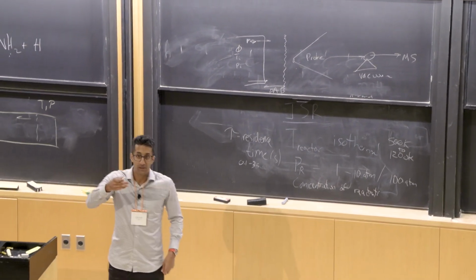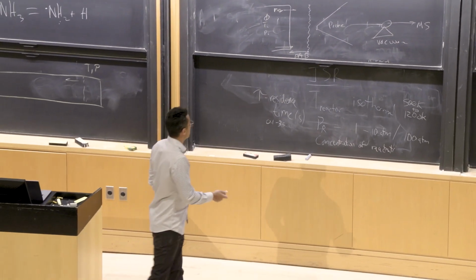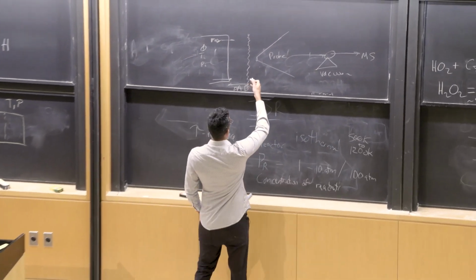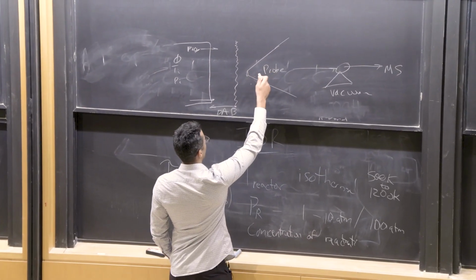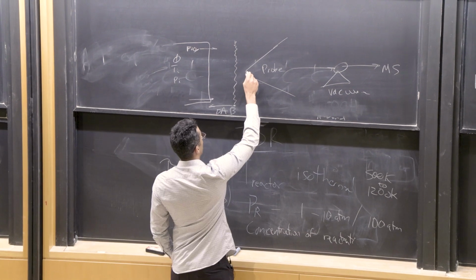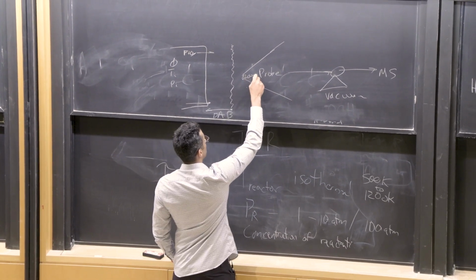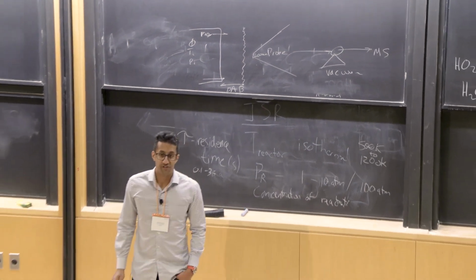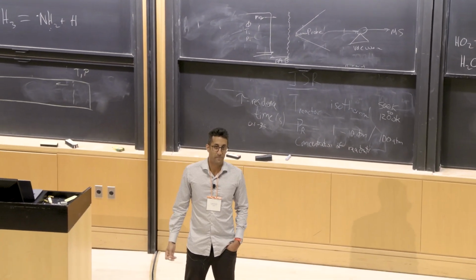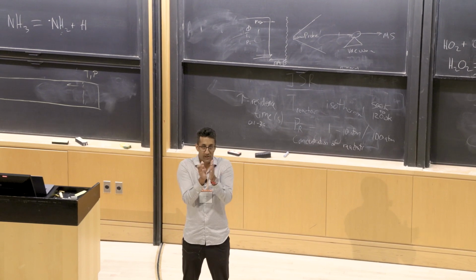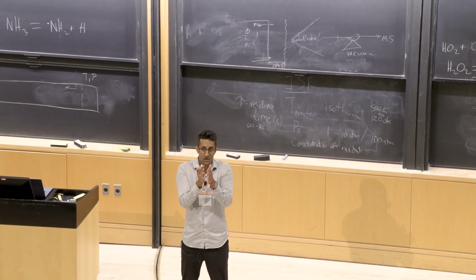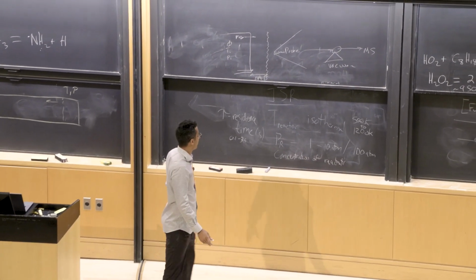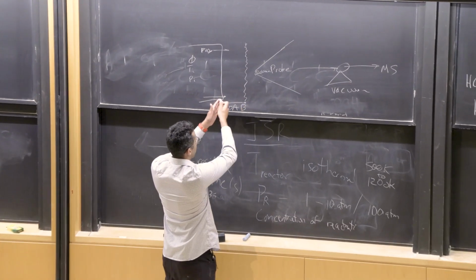Now, if you have a probe, this probe is a physical thing. It has some dimensions to it. The orifice might be 200 microns. So if you're trying to sample species, the physical probe is somewhat of a barrier, yeah? And if your flame is too close to the surface, you won't be able to even resolve anything.